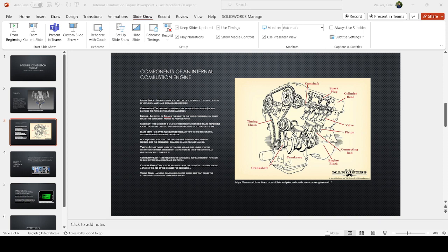It shows the engine block itself. They're most of the time made out of aluminum or steel, rarely made out of iron or something of that nature, a different material. Basically, what that does is it's the main housing for the engine itself. Inside of that, you can see the crankshaft just a little farther up, and the crankshaft converts the reciprocating motion, which is an up and down motion of the piston, and it creates a rotating motion from that.